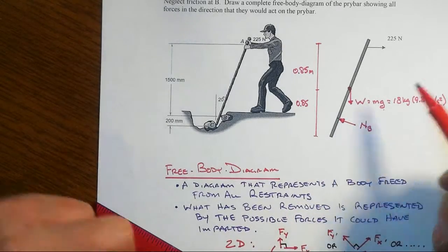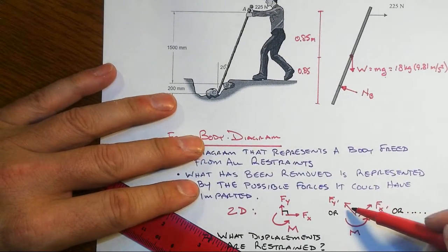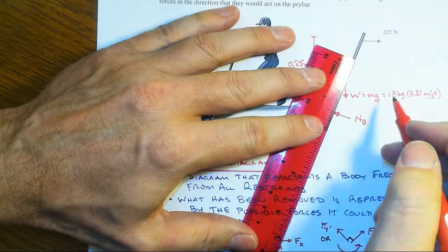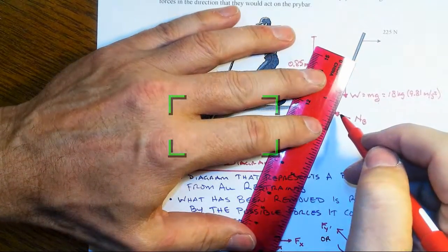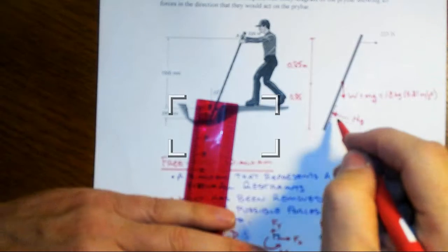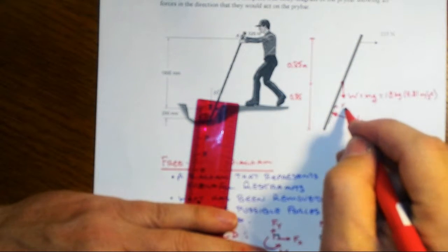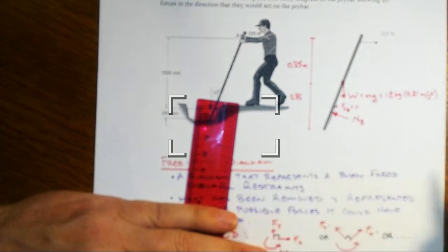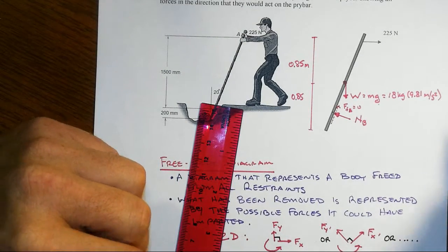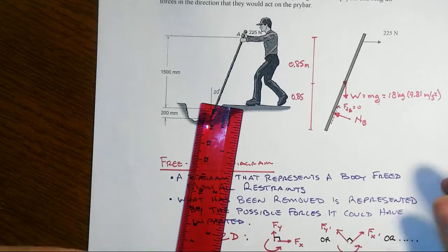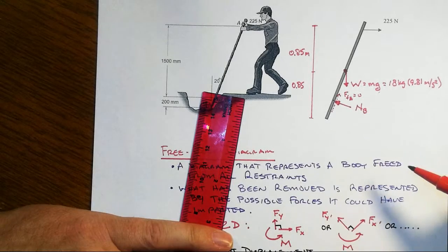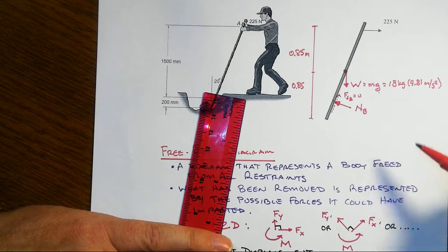And then the only other possible one, again, 2 orthogonal forces, right? So the only other possible force would be one that is parallel, but we're told to neglect friction at B. So that possible frictional force at B is going to be 0. We don't even need to show it, but I do here just to emphasize. In any situation there, we've only got 2 possible forces to represent, and we're told the parallel one, the frictional one, is going to be 0. We only have the normal.